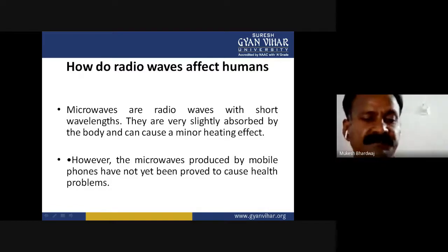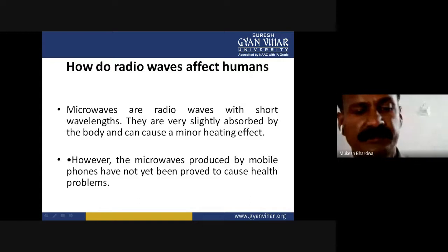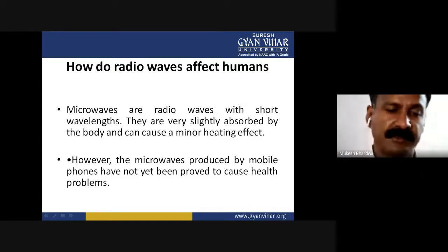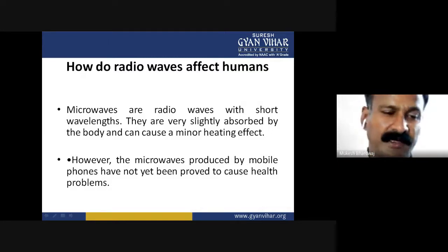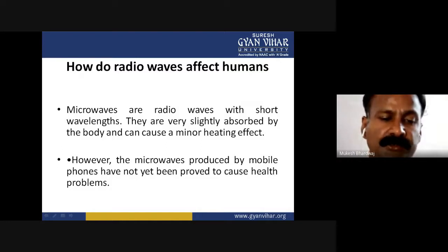The frequencies specified in the USA for these applications are 915 megahertz, 2450 megahertz, 5800 megahertz, 10525 megahertz, and 20125 megahertz. Industrial applications of microwaves include measurement of thickness of metal sheets in rolling mills, continuous measurement of diameter of wires, measurement and monitoring of moisture content, heating, cooking, and processing of food. Medical applications include diathermy, cancer treatment, etc.